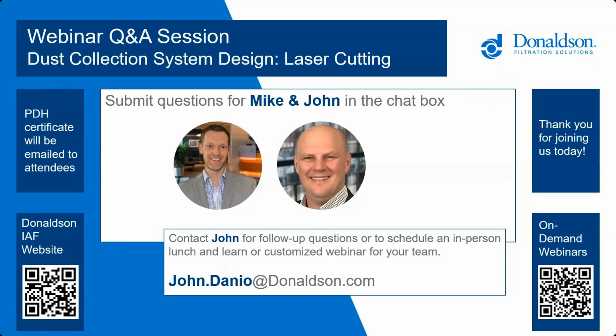But yes, condensation would be a concern because cartridge collectors perform their best when the dust is dry and they're in a dry environment. So typically, we would want to make sure that the collector, like a package collector, which we discussed earlier, has a rain hood over the exhaust to eliminate moisture from getting into the collector. And then we'd also want to make sure that you have sufficient ductwork. We mentioned spiral duct, which could allow rain to entrain inside the duct and then be pulled into the collector. You would just want to make sure you avoid that.